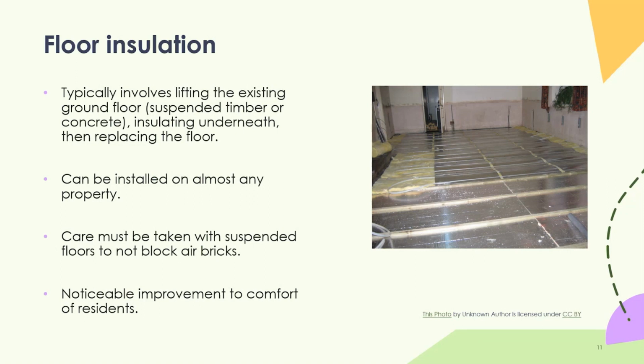If you're working with suspended floors, you basically need to be aware to maintain the airflow under that floor. So at the same time, checking that there are no obstructions to the air bricks. Basically what you're doing is separating the flow of air under the floor from being able to leak back into the property above. So you have an airtight membrane with your insulation, and then the floor is installed back on top of the joists.